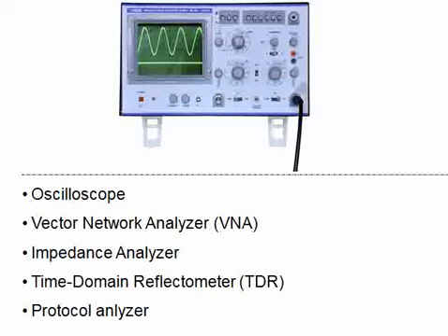Right now, if the product works straight away, yes, it is okay. But if the product doesn't work, and when you start debugging, when we say product doesn't work, for example, let us assume we have one high-speed interface. Well, let us take a simple USB 2.0. Let's not go to gigahertz range. USB 2.0, and let us assume it's not working. So you will check drivers, you will check any shorts for those signals, you will check the continuity of those signals. So you will do several things, right? But how do you ensure that you have routed the 90 ohm differential signals correctly, and that might be the reason why your PCB is not working?